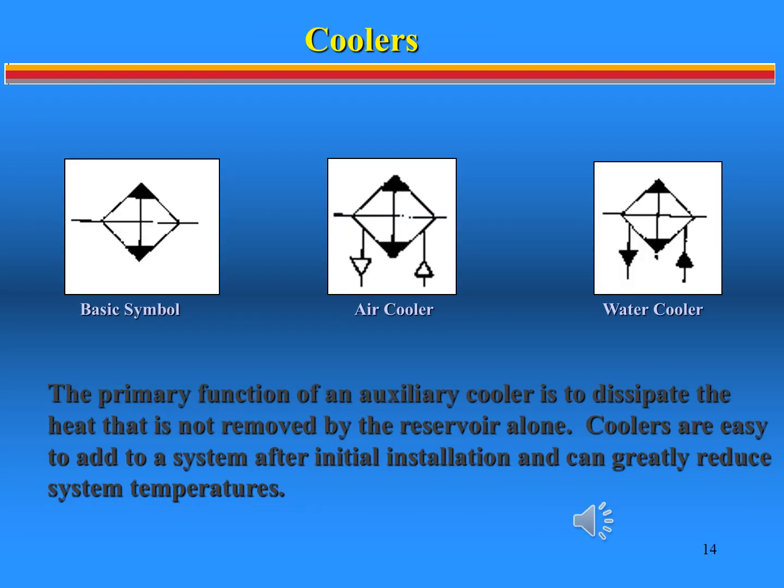These are symbols for coolers used in hydraulic systems. Heat kills hydraulic systems. That's why hydraulic oil coolers are widely used in a diverse range of agricultural, mobile, manufacturing, and industrial settings. They remove excess heat generated by energy losses in a system, as well as that from external sources such as engines, furnaces, and even the surrounding environment.